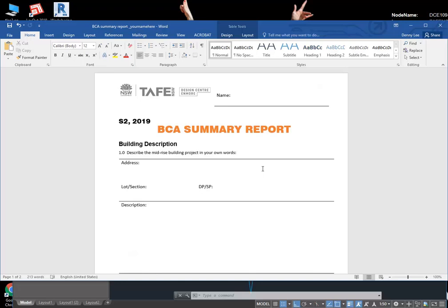But the other thing that could affect the ground floor is if you go for a ducted air conditioning system, then you may need a plant room on the ground floor. For the sake of this report, I would do that. If you have split systems, then you'll have to have the compressors outside the building by the back, or on the facade, which is harder than just putting a plant room on the ground floor.